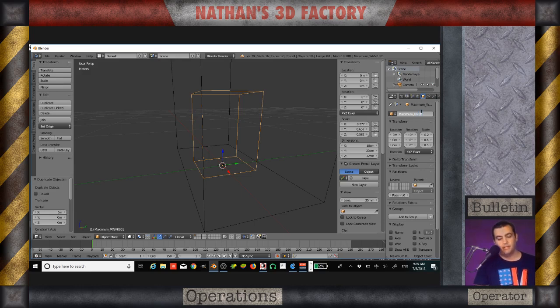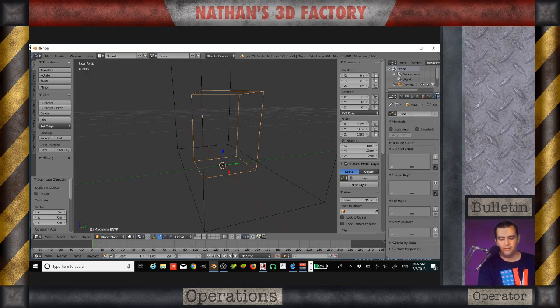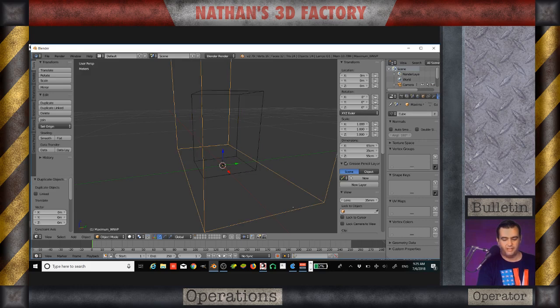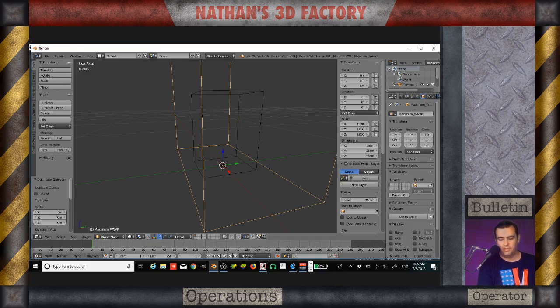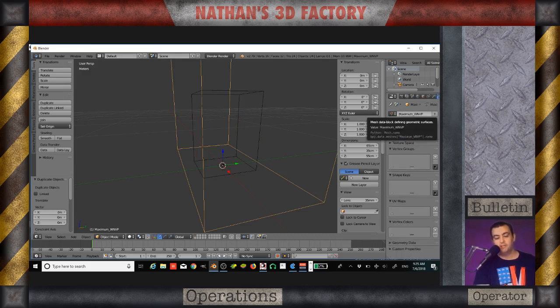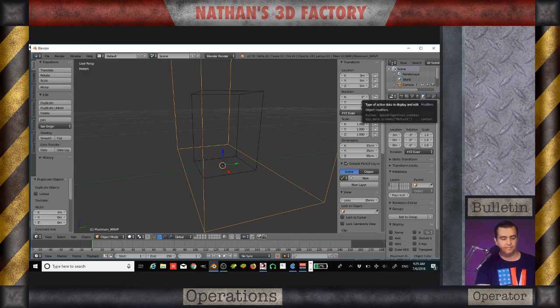VNVP. So that's going to be my naming system. I'm going to do the acronym for all the stuff that's available in the material. You can name it however you want. So this is going to be available for everyone to use. Okay. Same there. And I did not rename the mesh data like I was supposed to on the last one. So let's just fix that. Okay. So that one, Control C, Control V. There we go. So that is something that we need to know as we're doing this, is that we need to not only rename the mesh, or I should say the object, but also the mesh data.